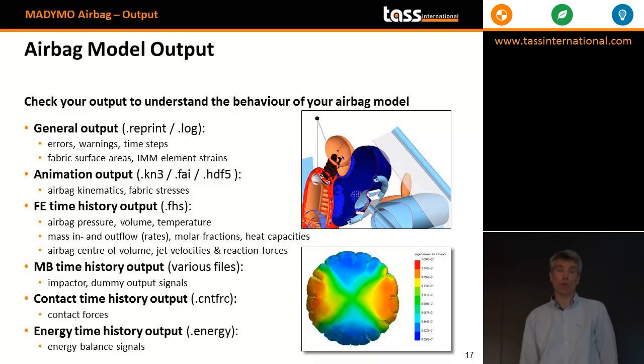And at the end, the energy might not be that relevant, but typically the energy balance is used to check the robustness of your solution. The total energy, obviously, has to remain constant. If you see large spikes or noise in one of the total energy functions, maybe the total, but it can also be in the contact, then it might be an indication that there is something wrong in your simulation. For that I consider the energy balance a good way to check the robustness of your simulation.